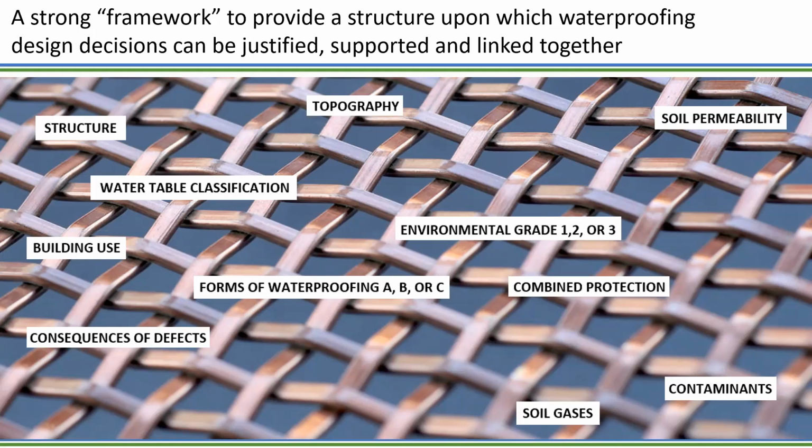Consequences, defects. So when I design a system, I almost have to think what can go wrong, who can damage what, what gets covered up, what's the time of year, what's the temperature going to be, will the product be appropriate to be installed at 2 degrees C, things like that. So that can all engender defects on site. Site conditions are less than perfect. Yeah, I'm sure we'll all agree. There's plenty of scope for less than adequate workmanship, damage, people cutting corners, all sorts of things.